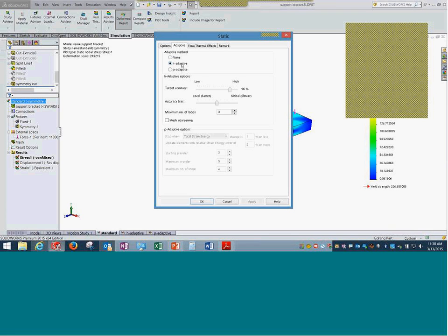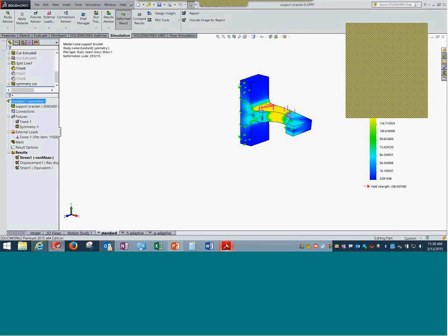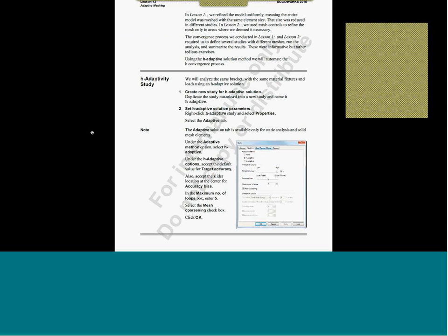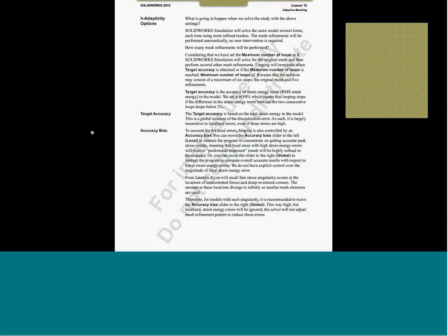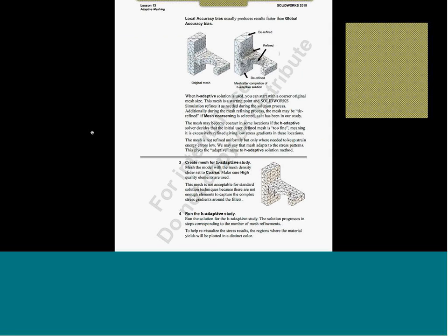It is better to do this mesh convergence manually, on your own. It is an option at the part level, wherein we can refine the mesh, understand where we want a better mesh and where it is okay to have a coarser mesh. Thereon we can give these values manually and then decide and go ahead with it. Okay, I can discuss or explain H adaptive and P adaptive on these topics.